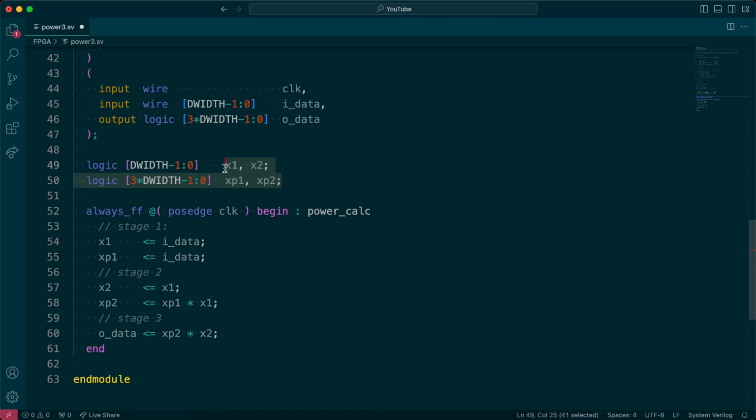These 2 are each 8 bits, and these 2 are each 24-bit values. So I'm using resources on the FPGA to store the data. So everything is a trade-off. I'm improving the throughput, so what am I giving up? In this example, it was the area.